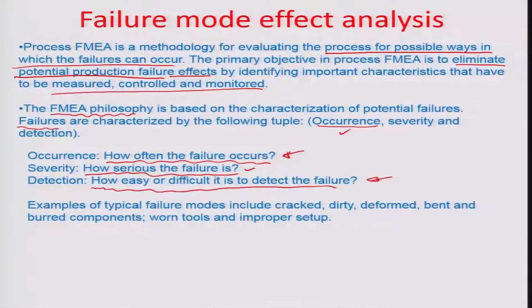So you are covering all aspects of a failure mode, and if these aspects are covered in a very organized manner and everywhere there is some improvement which is given, maybe in the modes in which detection of failure is possible, or even doing something with the design improvement where there is a lessening of the severity if this failure happens, or even something related to a countermeasure which may just reduce the occurrence of the failure, it is ensuring that the product is good quality, okay. And that's exactly what the whole essence is of FMEA activities.